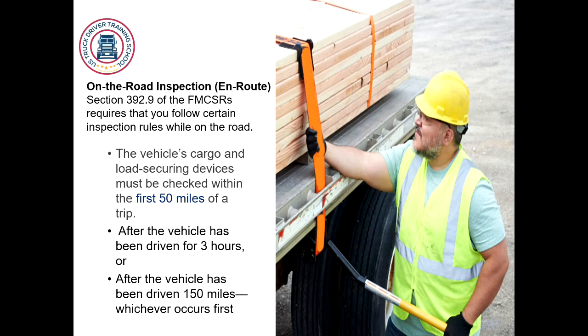After the first 50 miles of the trip, the vehicle's cargo and load securing devices must be re-examined whenever you make a change in duty status, after the vehicle has been driven for 3 hours, or after the vehicle has been driven for 150 miles, whichever occurs first.